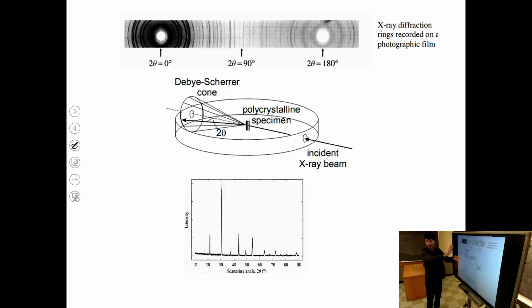So if the crystallites are all randomly oriented, we are not going to get just one angle 2 theta, but we are going to have a ring. All possible angles around the incident beam from all the little pieces of the polycrystalline material will be allowed. And so the X-ray diffraction pattern will look like a set of concentric rings centered around the central beam. This is from the averaging over all, summing up all the possible orientations of the polycrystalline samples.